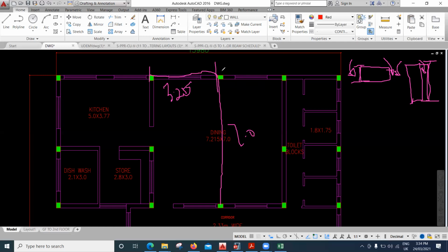So even though from the architect's point of view and from an aesthetic point of view, this column looks good, it is getting flush with the wall, from a structural point of view, this column will not work out, because we are putting the load on the minor axis of the column. So the best practice is that you have to keep your column orientation in this way. You have to place the column orientation in this way.